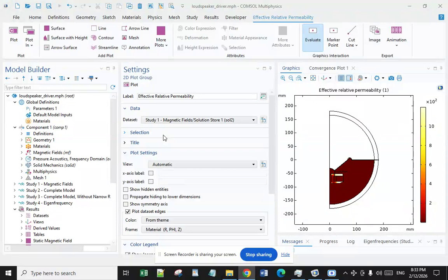In some cases, one or two peak responses may be observed with the increase of bias field. In some cases, the response can be improved significantly with the change of relative direction between the bias magnetic field and the AC magnetic field. Quantitatively, the magnetostriction may be described in similar mathematical formats as piezoelectric constants. Empirically, a lot of experience is needed to fully understand the magnetostriction phenomena.